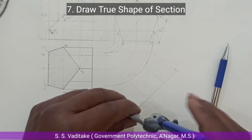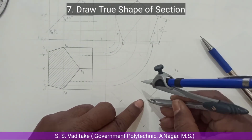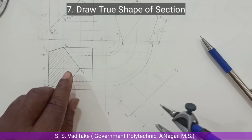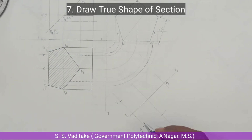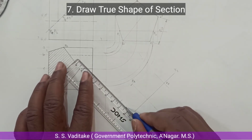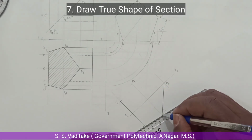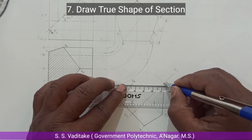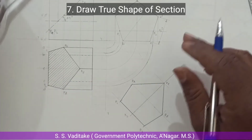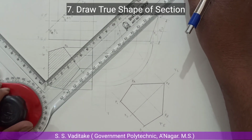Now take the distance of point 1 in the top view and transfer it on the respective edges. Take the distance of point A and point D and transfer it. Point E will lie on x1, y1. So join all these points by using a scale. The outline for the true shape of the section is available.